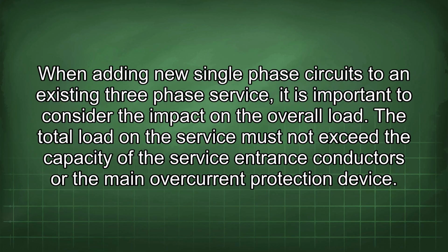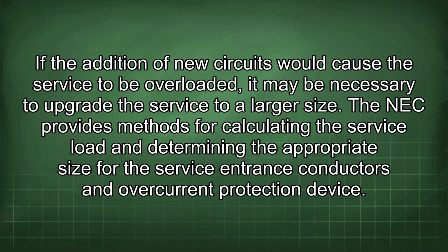When adding new single-phase circuits to an existing three-phase service, it is important to consider the impact on the overall load. The total load in the service must not exceed the capacity of the service entrance conductors or the main overcurrent protection device. If the addition of new circuits would cause the service to be overloaded, it may be necessary to upgrade the service to a larger size.